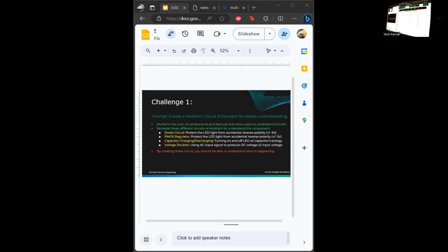Like, should it be VGS instead? VGS is the threshold. I don't know if that's always true. I know for how they explained it, it's mainly like, usually if this voltage is less than this one, then... It's not always true, in my experience. It's better to look at VGS threshold voltage instead of the drain voltage, yeah. I see.